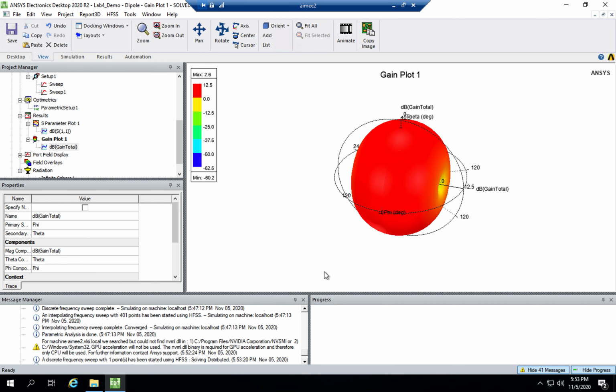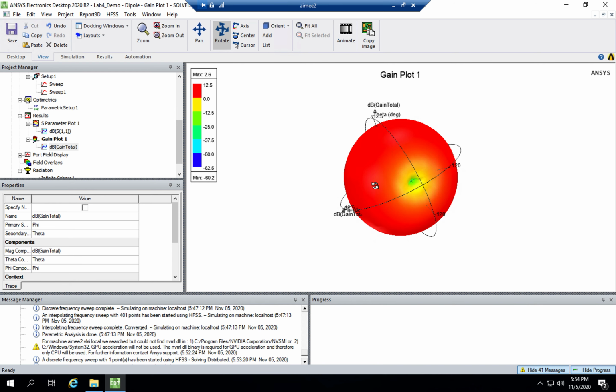All right, so this is what the radiation pattern is. It's a distribution of the power surrounding the antenna. So it tells you where the power goes when it radiates out of the dipole antenna. So in this case, you can see here that there is high power, which is the red, in these certain directions. There is a null or a zero along the dipole, which makes sense.